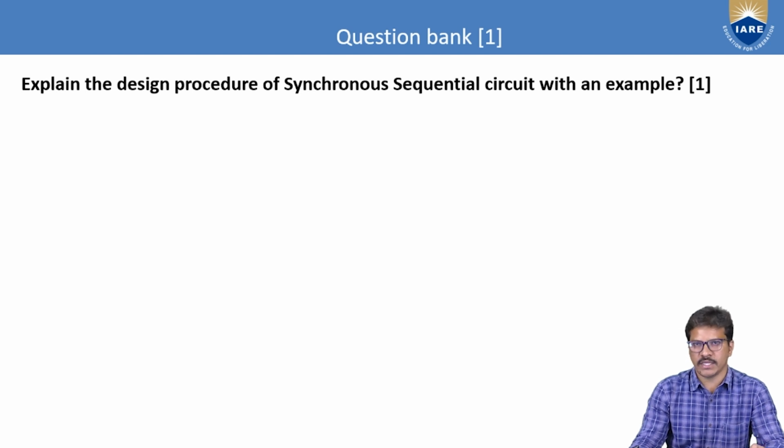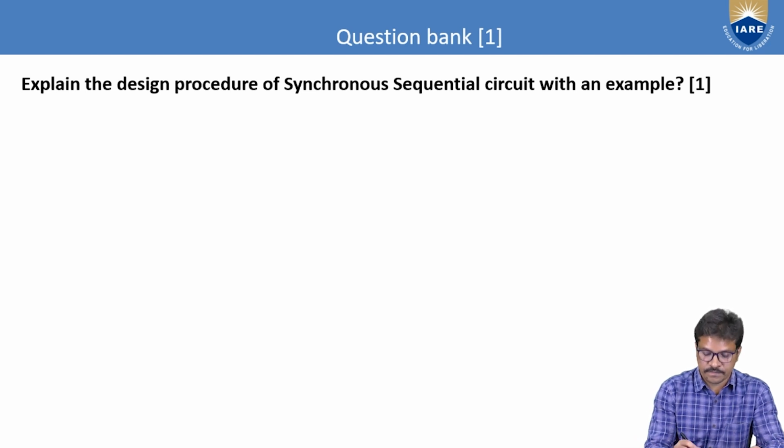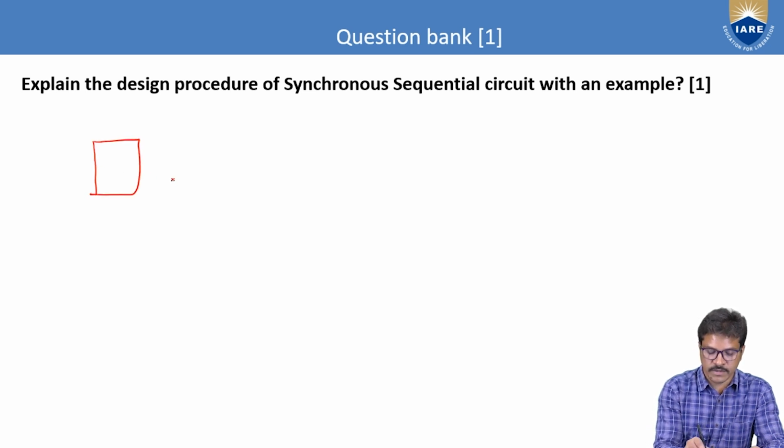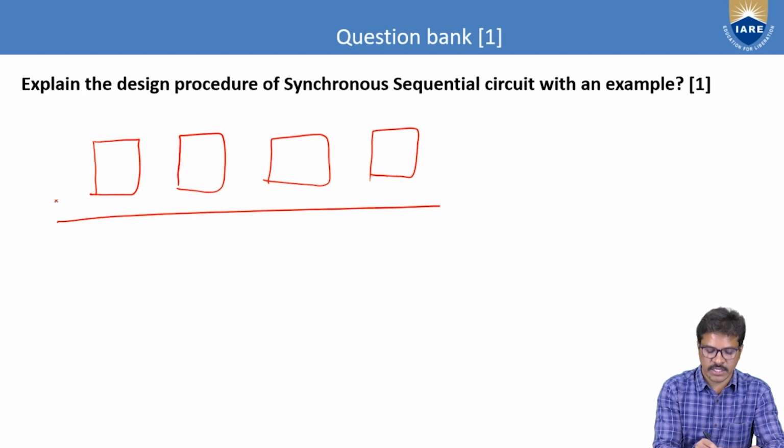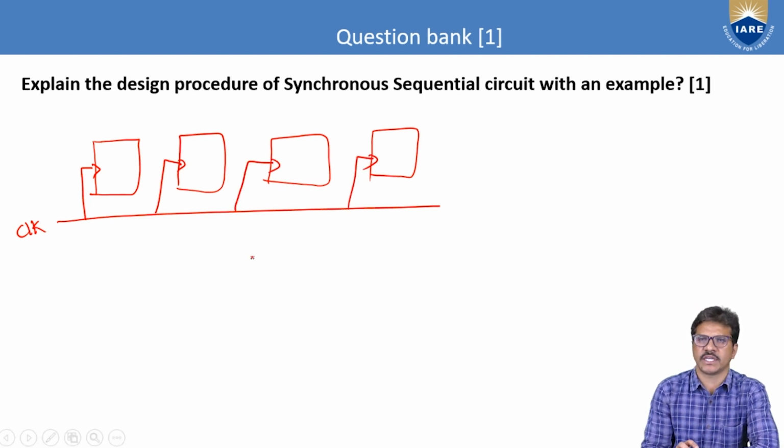Any synchronous sequential circuit can take that conversion, like the states are simply a counting up counter, simply a down counter, simply a counting of a sequence using synchronous sequential circuit. Basically, synchronous sequential circuits are, if you take any 4 flip-flops, all 4 flip-flops are parallelly connected with a single clock. This is nothing but a synchronous sequential circuit.